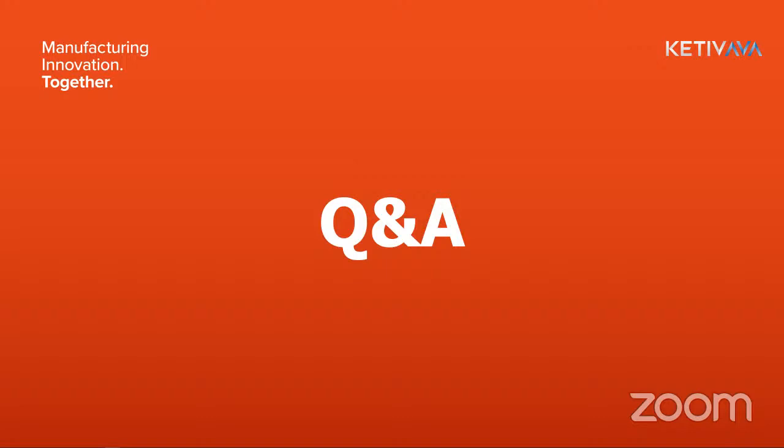Looking at the questions now, we got some from Eric. Can a custom UCS be used in an iPart factory? I believe so. I don't think it's much different than just having a regular work feature like a plane or an axis. But have you tried using any of the UCS stuff with iParts, Marco? I have not yet, actually. No problem. I'm pretty confident it can be used with iPart factories, and I'm assuming it's going to be really similar to work features in that regard, Eric. And like I discussed already, it is very similar.